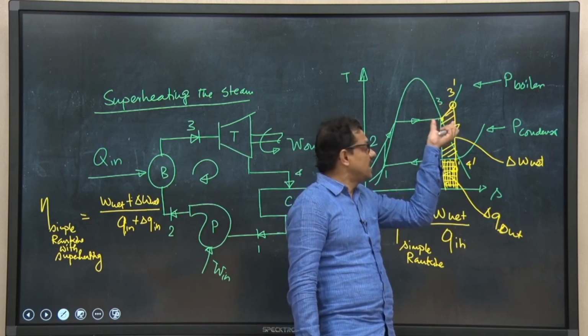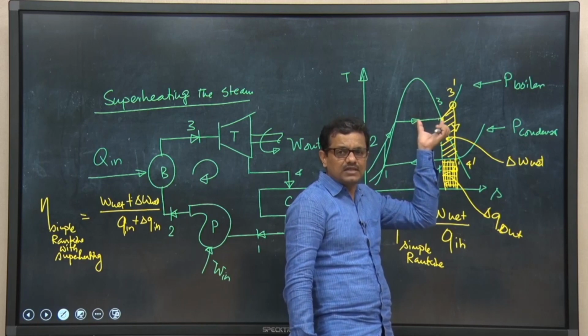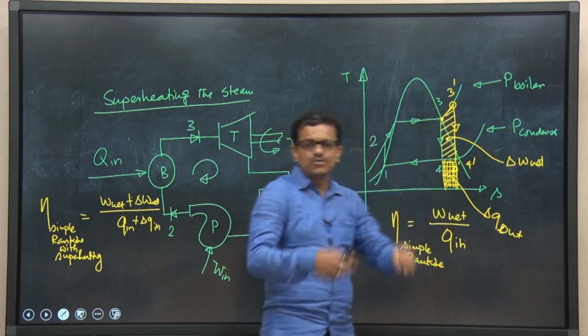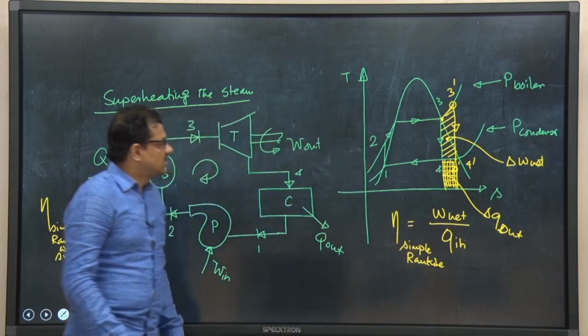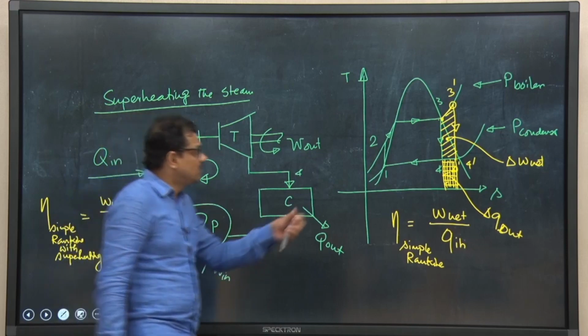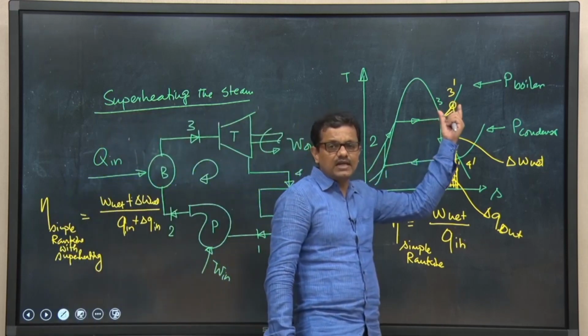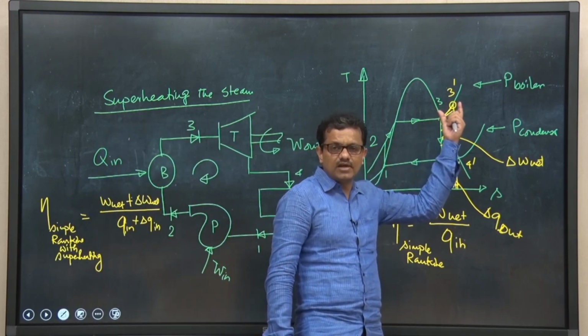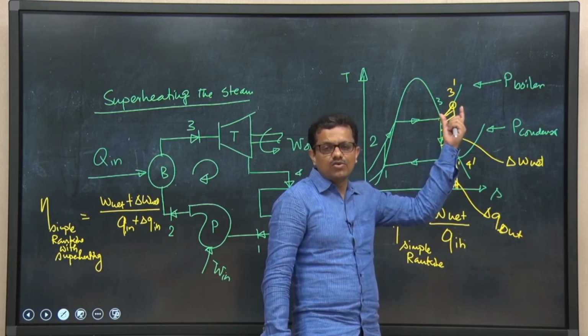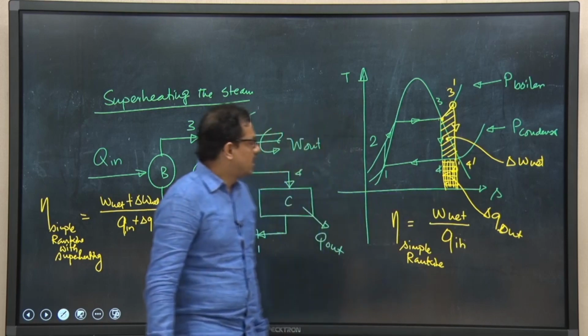If we allow the boiler to operate at a low pressure, then the degree of superheat needed to achieve high thermal efficiency will be very high. If we want a high degree of superheat, the arrangement will be much more complex, and initial as well as operational costs will be higher.